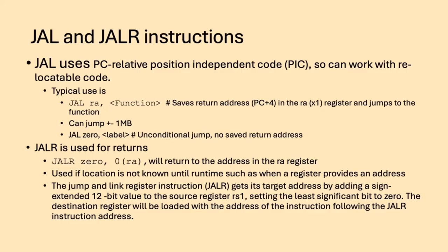A summary of the JAL and JALR instructions is shown here. Note that JAL uses program counter relative addressing to generate position-independent code. Since the code works with addresses relative to the program counter, the code is agnostic as to where it's placed in absolute memory.